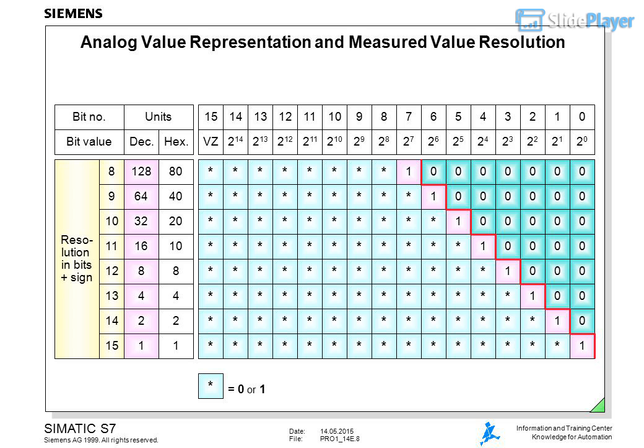Integration time in ms, resolution in bits, interference frequency suppression in Hz. 2.5 ms with 9 bits plus sign bit; 16.6 ms with 12 bits plus sign bit at 60 Hz; 20 ms with 12 bits plus sign bit; 100 ms with 14 bits plus sign bit at 10 Hz. Accuracy: resolutions of between 8 and 15 bits are possible, depending on the type of module.